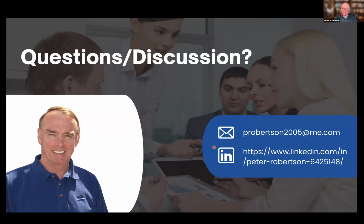Because the cone penetration is already undrained, you can estimate it directly from the sleeve friction. In silts or low plastic clays, you get it directly from the sleeve resistance. But in sands where the penetration is drained, you get it through an empirical correlation that's supported primarily by case histories. It's also summarized in the CPT guide.